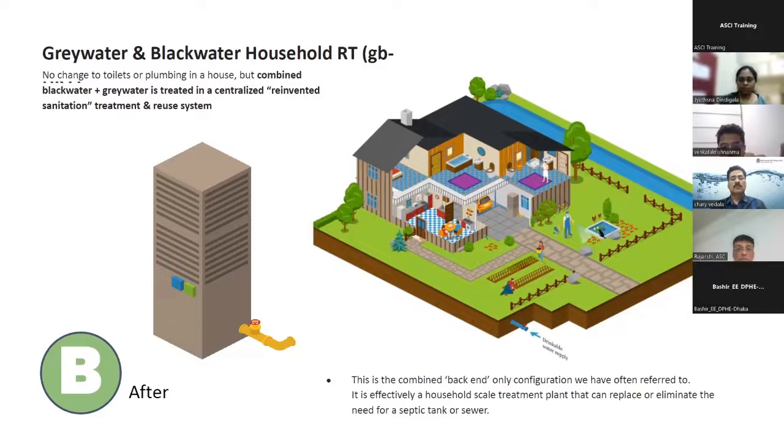You can have this sitting at a household level with multiple toilets or bathrooms, or in a building with 8 houses or so on. You have a treatment unit where the solids are separated and treated, possibly within the restroom, at the back end of the toilet bowl itself, or centrally at a house level, or maybe at a floor level. The philosophy remains the same: pathogens are removed from the solids and the water is treated to be reused.